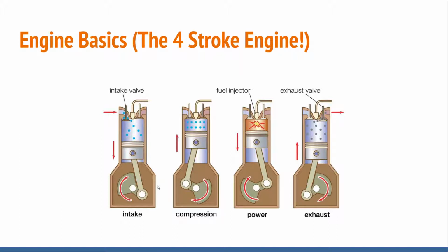Our second stroke is compression. The piston is coming up, compressing the air-fuel mixture. Third stroke we have is the power stroke. That is when the spark plug fires and ignites the air-fuel mixture. And then finally the exhaust stroke. The piston comes down after the power stroke, starts coming back up, and it exhausts all of that spent gases in the exhaust stroke. So to be clear, the spark plug fires every other time the piston comes to the top of the cylinder.